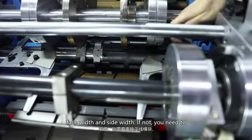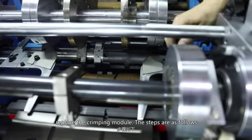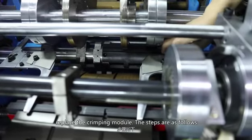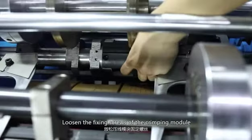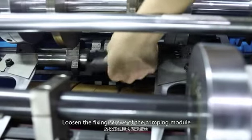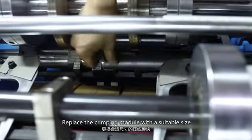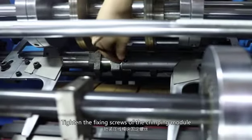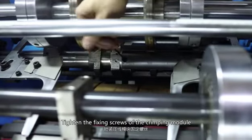If not, you need to replace the crimping module. The steps are as follows. Loosen the fixing screws of the crimping module. Replace the crimping module with a suitable size. Tighten the fixing screws of the crimping module.